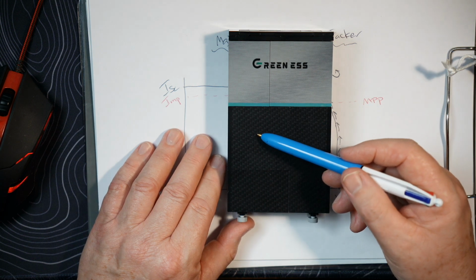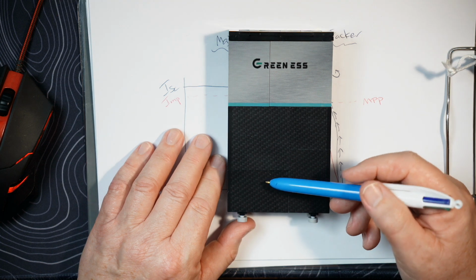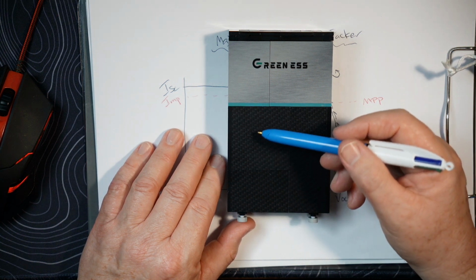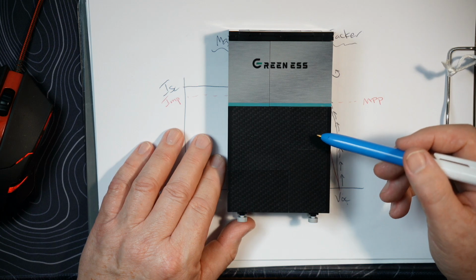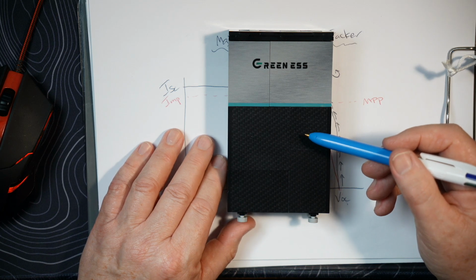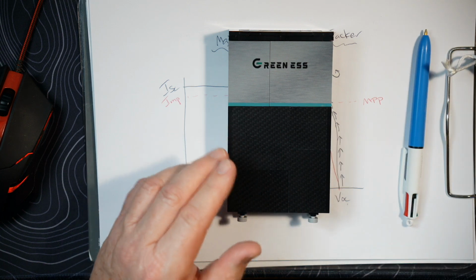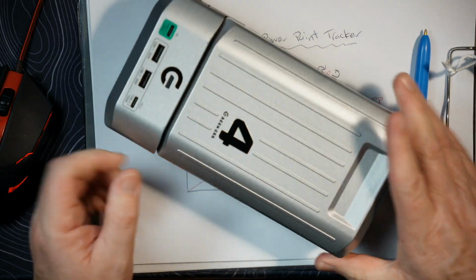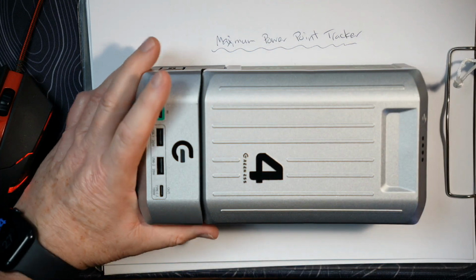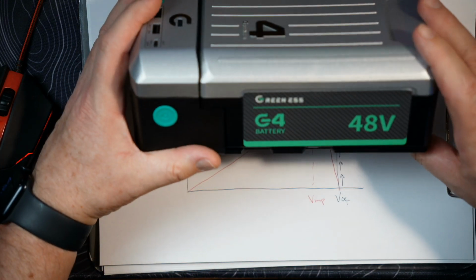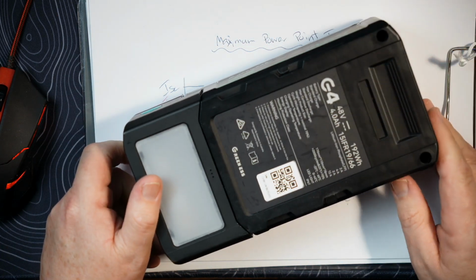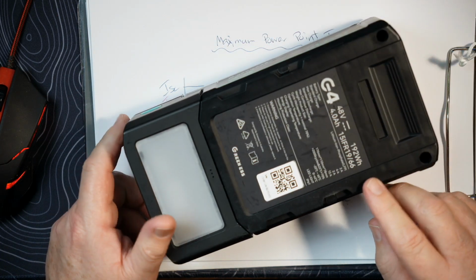In this half, we've got two, I think they're 5 kilowatt hour battery modules, which are permanently installed. But in this half, we've got removable power banks. Yeah, and I've got one right here. And this is the actual unit. So this thing here is a 48 volt 4 amp hour unit, so it's 192 watt hours.